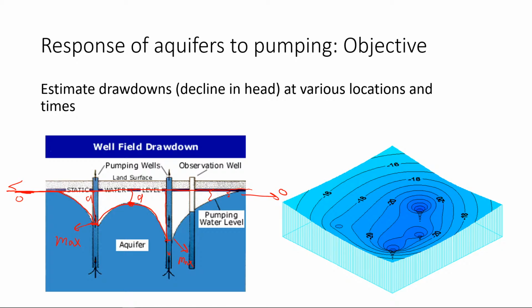For example, you see this cone of depression takes a circular shape. This circular shape is very important because we will learn how to take advantage of this symmetry. The cone of depression has a symmetry, so you get this circle. Here is the steepest gradient, and here is more gentle, and this is very gentle.